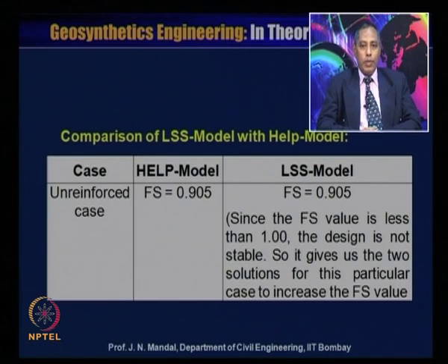So, it gives us two solutions for this particular case to increase the factor of safety value. We can go ahead with these two options. You can make the slope stable with a berm or an anchor, or you can provide geogrid or geotextile reinforcement to make it stable, when the factor of safety will be greater than 1.